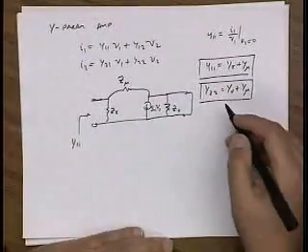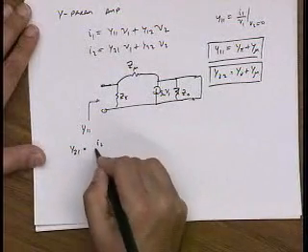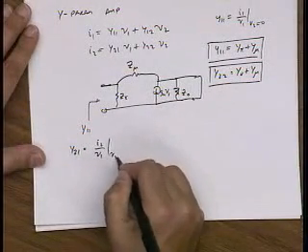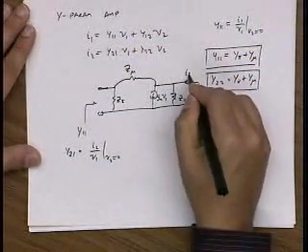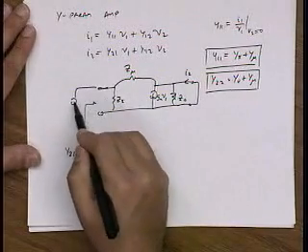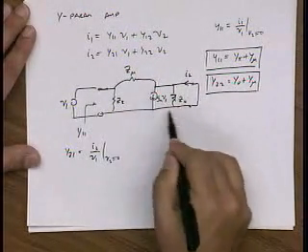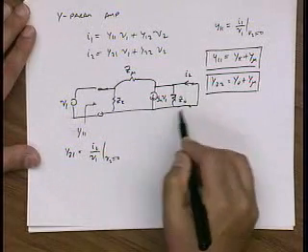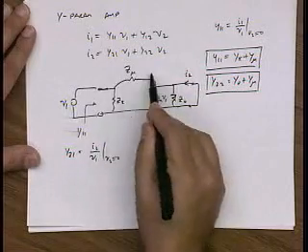And how about the transconductance? So Y21 is I2 over V1 when V2 is equal to 0. I'm interested in knowing this current I2 when I apply a voltage source V1 here. Well, that current is going to be exactly this current, the GM current, plus possibly this current, right?